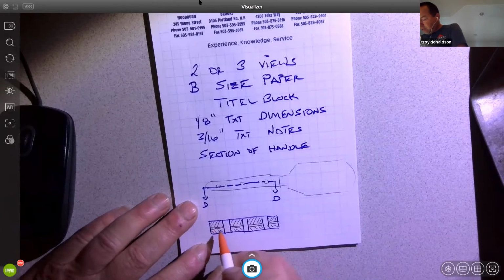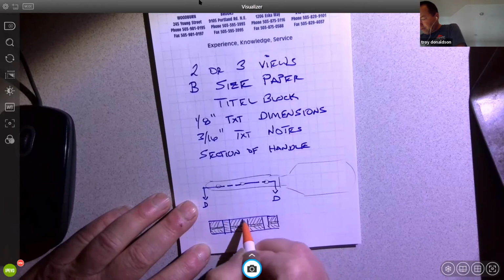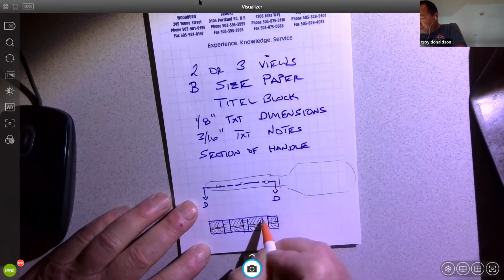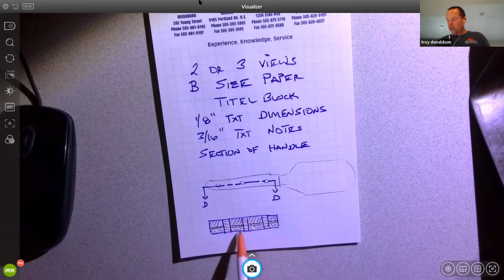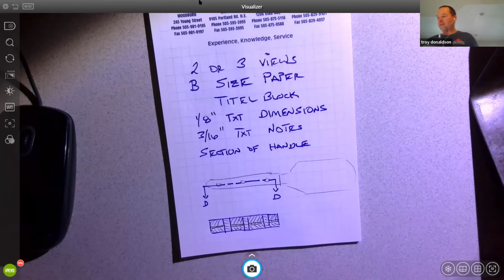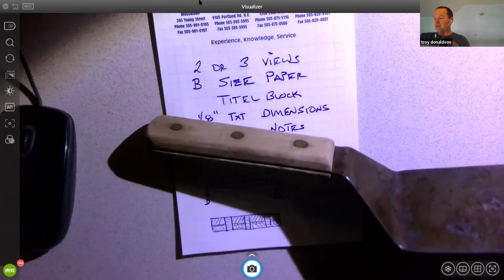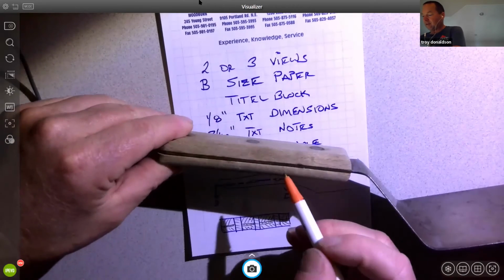And yes, this actually would get hatched too. And I don't really know, that's probably not even going to show up much. But then this one maybe is something like this, where none of them line up and none of them are horizontal. That's how we would do it. Each material would get its own hatch pattern. So the wood would get its own hatch pattern. And these could be the same. They're just 2 separate pieces on mine. So I probably would do them differently, like that, 2 separate pieces. Actually different thicknesses, right? This is thin, this is thick.